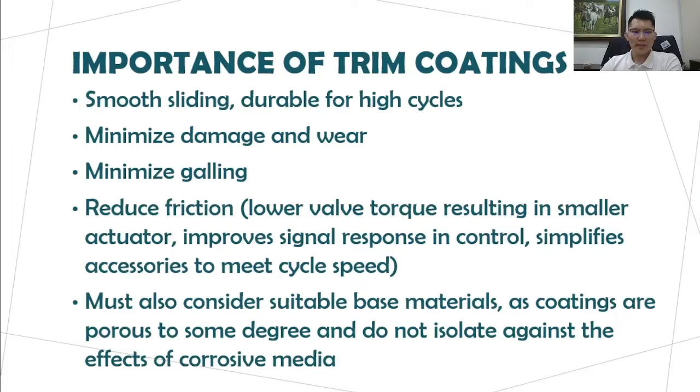So why is it so important to discuss the metal seat or trim coatings? Because a good selection of trim coating provides smooth sliding and is very durable, especially for high-cycle usage. Secondly, selecting the right hardness value for the coating can minimize trim damage and wear and tear. Also, it will minimize galling.